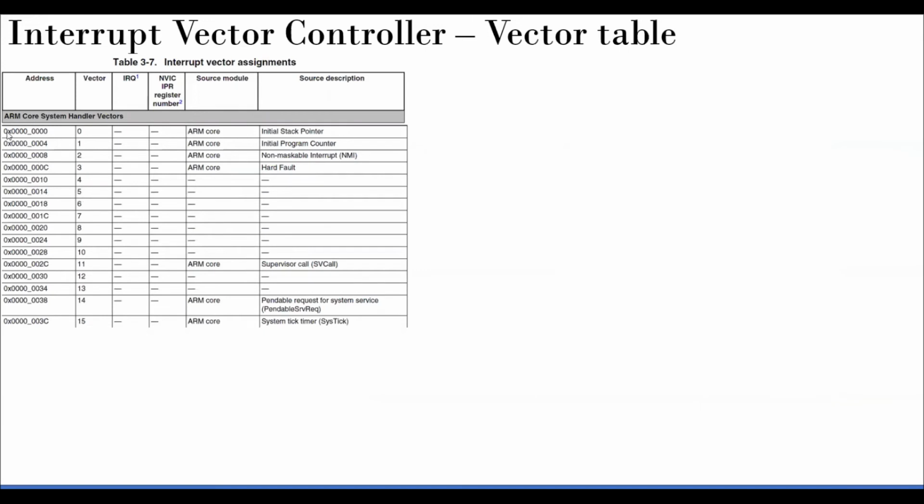For example, I just want to make it very clear to you. These are the addresses of the memory map. This is the very first address. Always remember that it is 00, all zeros, and that address has the pointer to the stack memory. So that has the starting address of the stack pointer. That's interesting. When you reset, everything gets reset, and the stack pointer will come to the first location of the stack, and that value will be lying here all the time whenever you reset the system. The next, of course, is 0 to 4, because this is 32 bit and each location is 8 bit.